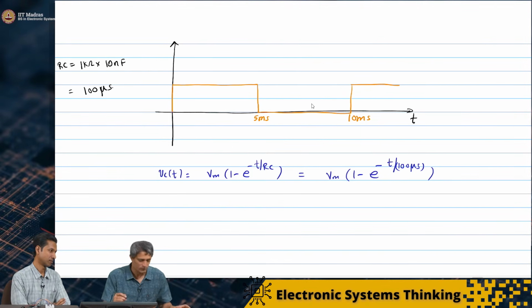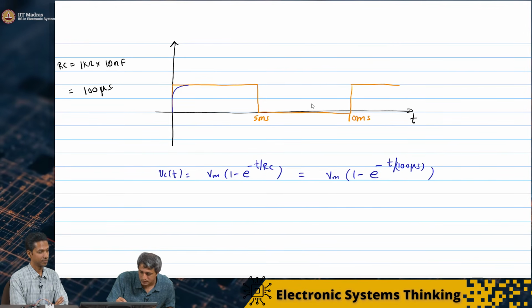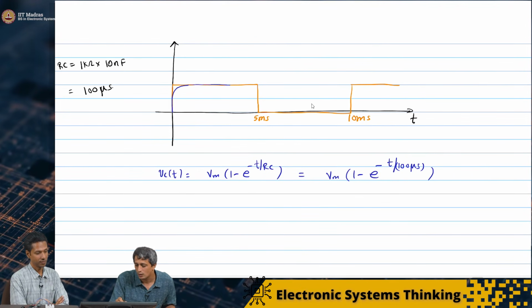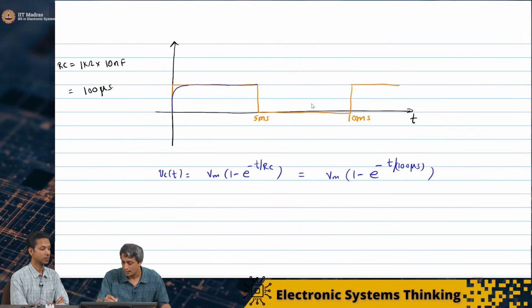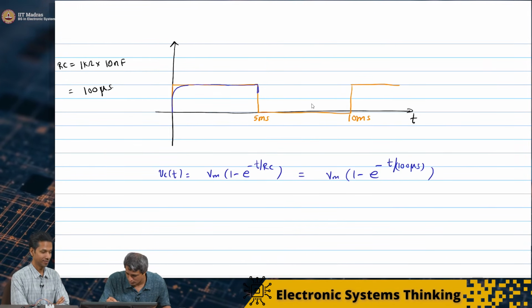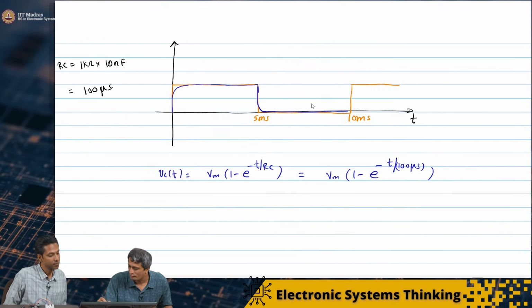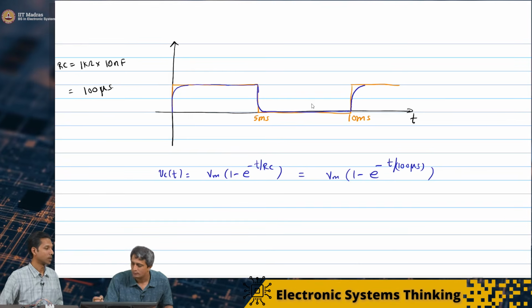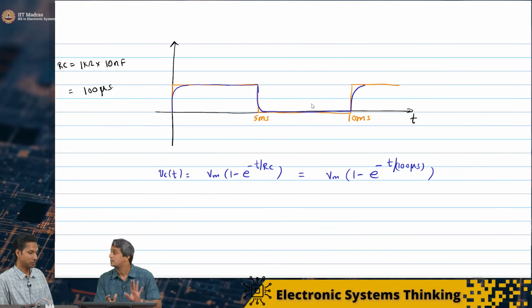It was not visible. In fact, the waveform was like this. It would go all the way. Now it wouldn't fall abruptly. That is also going to discharge, so it falls like this. But effectively, 5 milliseconds is infinite time for this circuit, because of the RC values.